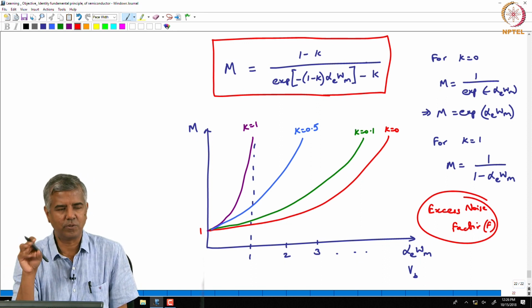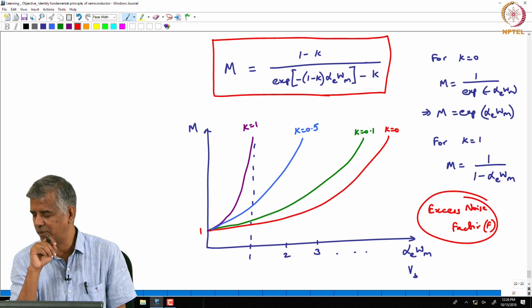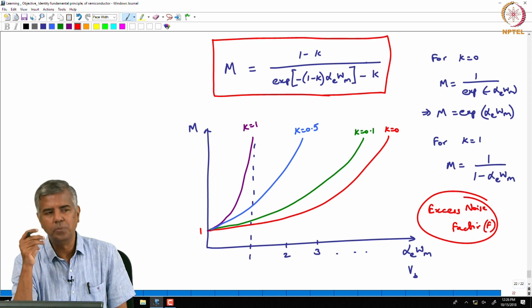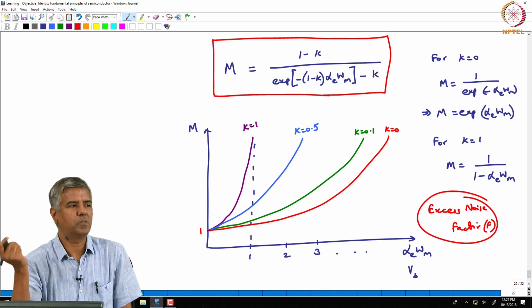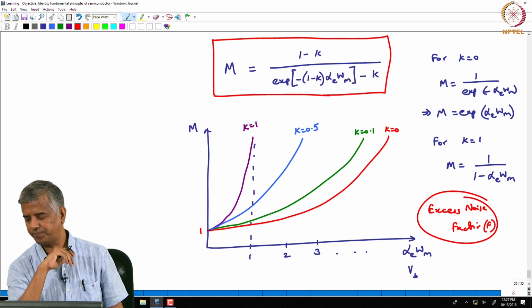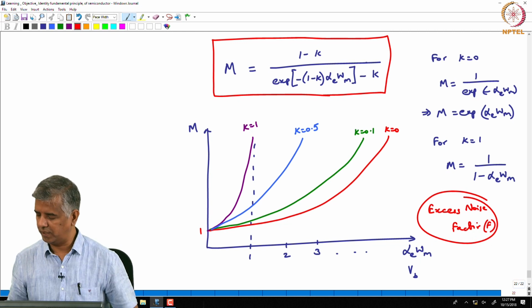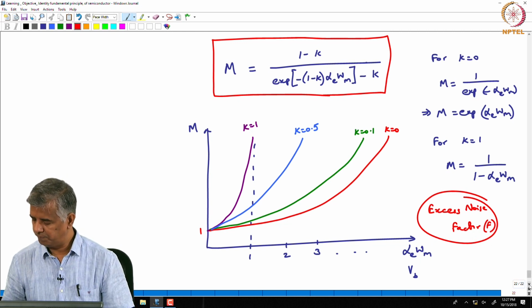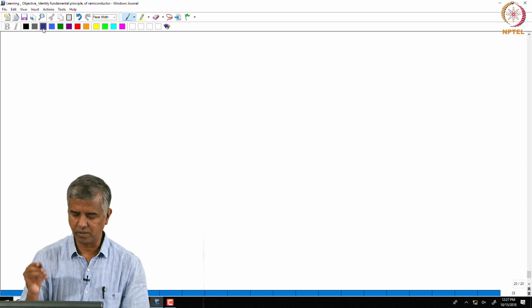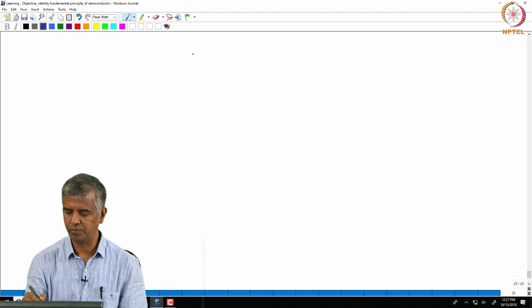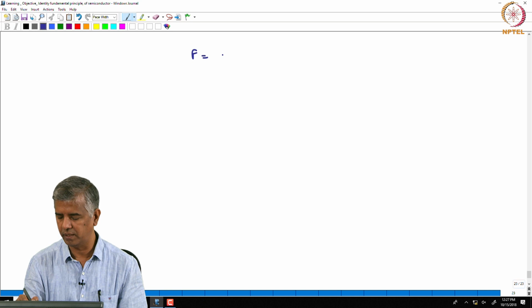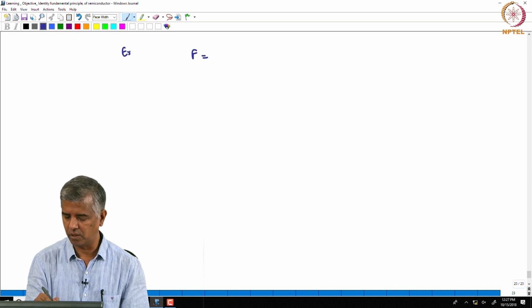We will come back and look at what is the basis of that in a few minutes, but beyond that noise process you may have extra noise because of this avalanche process. That is why it is called the excess noise factor. Now, the excess noise factor, I do not have a derivation for this, because the derivation is actually a very long derivation. I can give you an appropriate reference if you are interested, but this excess noise factor